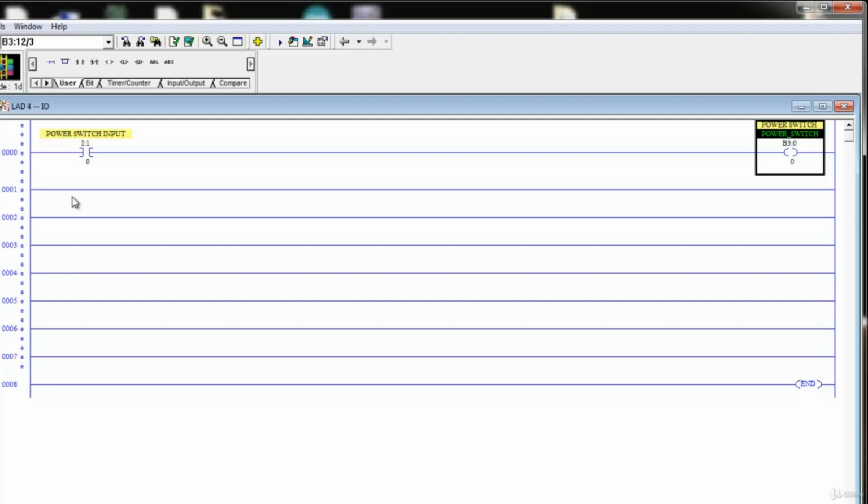The wise, the smart programmer will pull all of their I/O out of the logic and set it aside somewhere in a ladder or 4 ladders dedicated to I/O. And I10 is going to appear one place and one place only within this whole program, and that is right where it is right now in ladder 4, rung 0. Anywhere else will be this B3:0/0, and it might be 100 different places. That's fine. I will never need to change this bit.